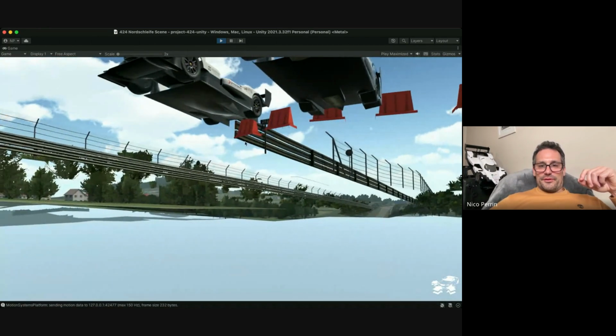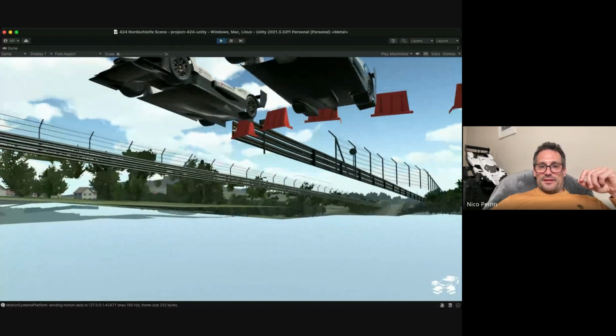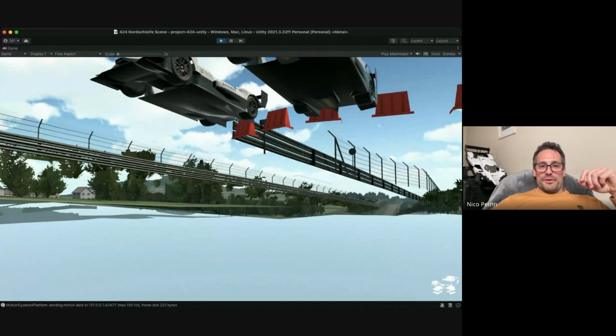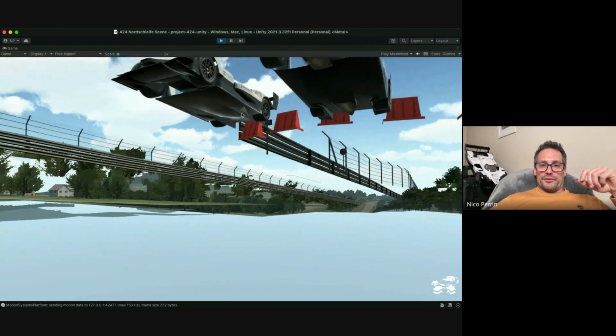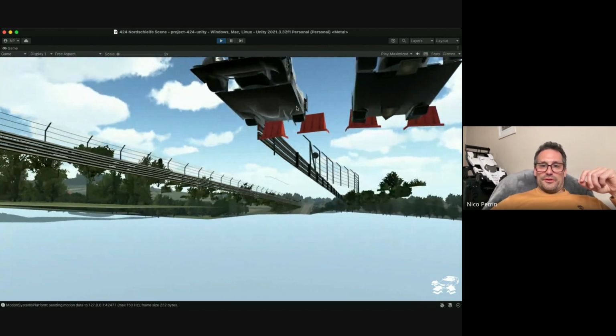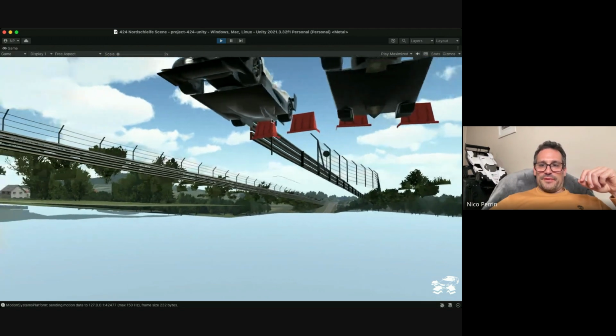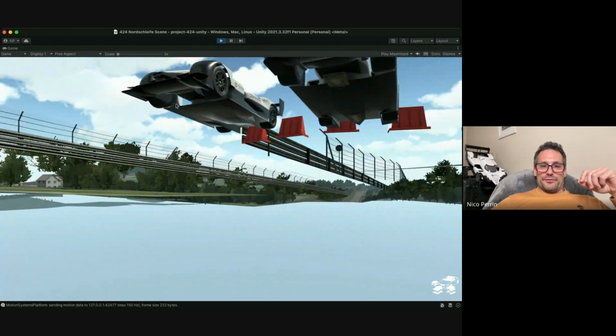Also the floor, we can look under the cars here. The floor is different. We've got a much bigger volume under the car here in terms of diffuser. This was still regulated by Le Mans. We went higher on the trailing edge and completely reworked the floor. The kick of the diffuser starts a bit earlier. I trimmed the front here. We've got more volume in this area, which was better for performance as well.